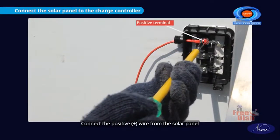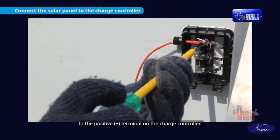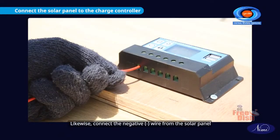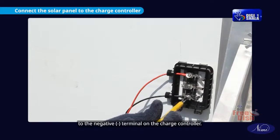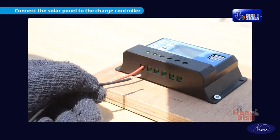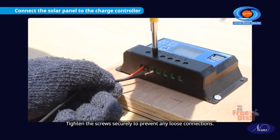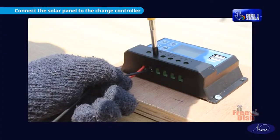Connect the positive wire from the solar panel to the positive terminal on the charge controller. Likewise, connect the negative wire from the solar panel to the negative terminal on the charge controller. Tighten the screws securely to prevent any loose connections.